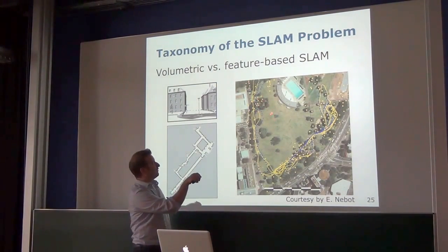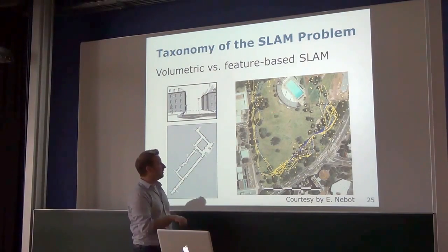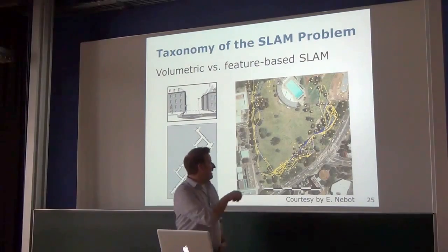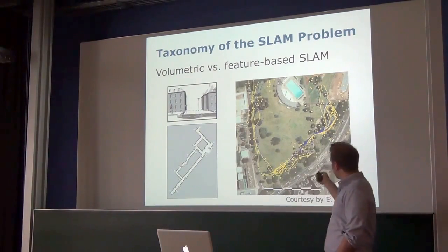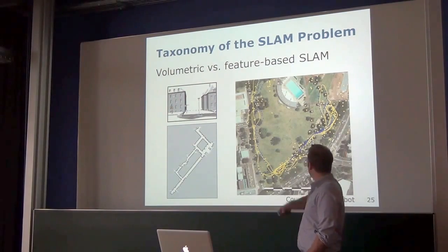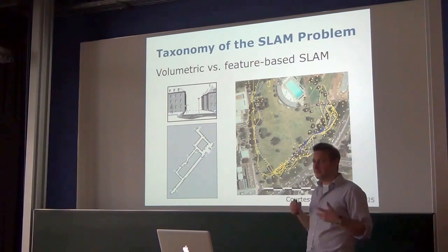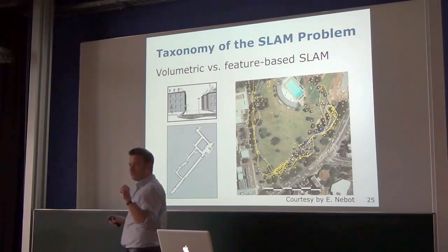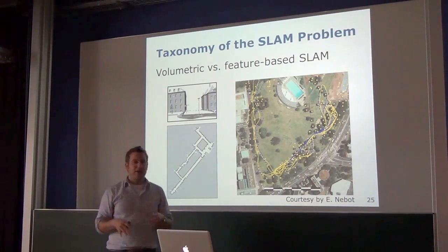You see sometimes that things are not that perfect, and there are erroneous measurements, maybe a person was standing there, no idea why. But what the system tries to do is estimate the position of those tree trunks shown here by those yellow dots. So the map representation is a collection of those yellow dots in their XY position. It's the feature-based approach.